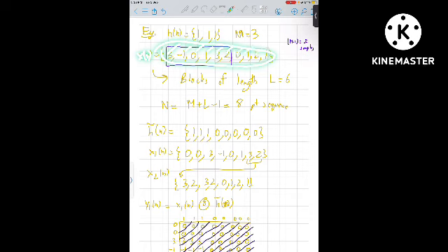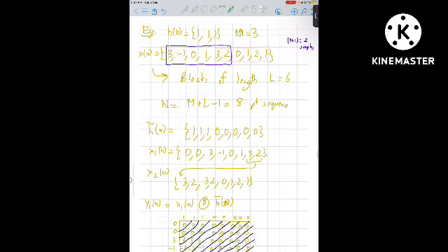So what will be your h tilde of n? It's 1 1 1, but we need 8 points, so we add 5 more zeros. H tilde of n is done. Now what are our blocks of data? We need to take blocks of length 6, 1 2 3 4 5 6. And then we also need to ensure that m minus 1, which is 2 samples from the previous one, are taken. So we take this subset of 6 and 2 of them overlap and save them.